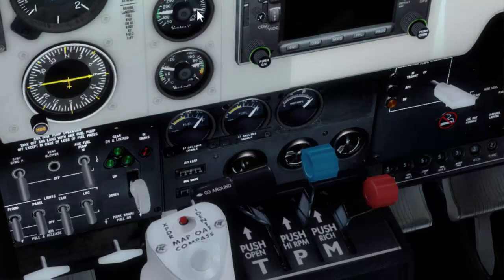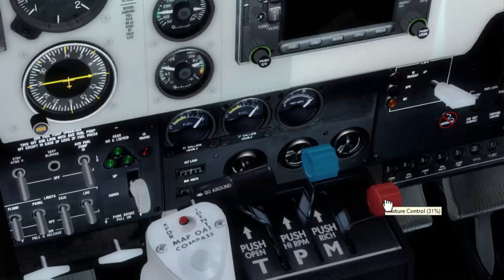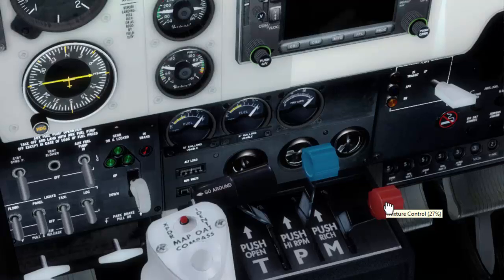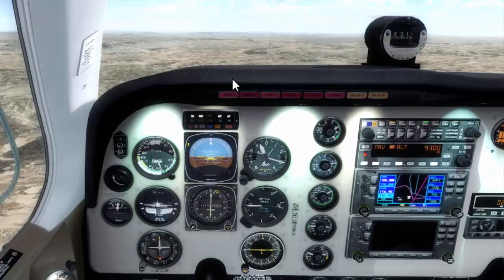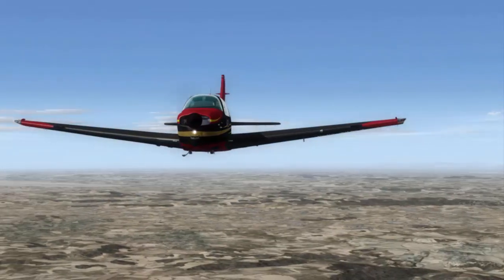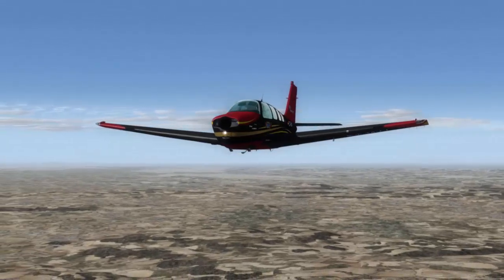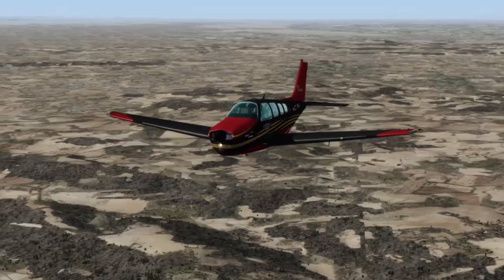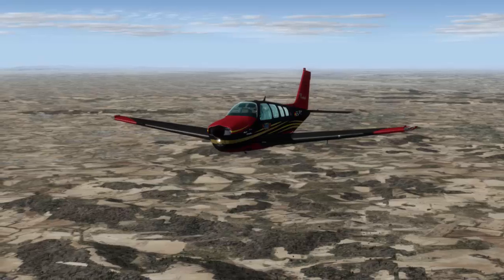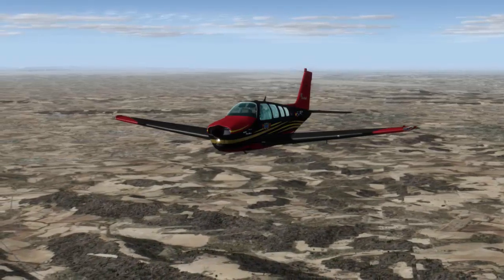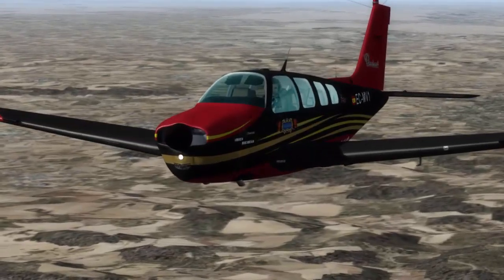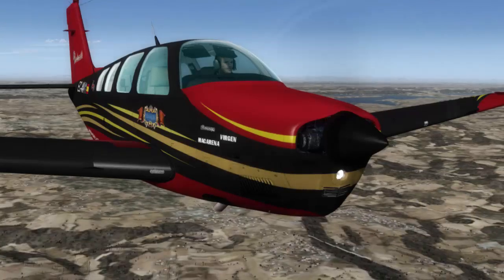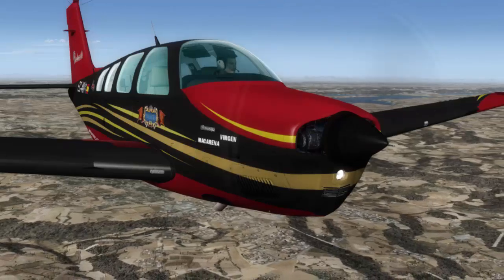And of course, if you take a look again at the EGT gauge, we will adjust our mixture to find the EGT peak, because we are ascending. Our goal is to move the red lever until we put that needle in its highest position. You don't see this right now because you don't have a view of the full cockpit, but I will move the red lever a bit forward, just so the EGT peak drops by 20 degrees, because in our cruise performance tables we need to fly relative to the EGT peak, with a reference of 20 degrees rich or 20 degrees lean. That will make the difference in whether we are flying in rich mixture mode or lean mixture mode.